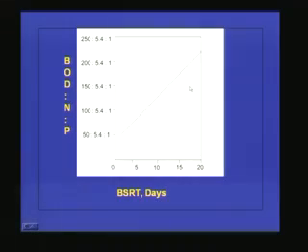What I mean is, if some industrial wastewater is there and there is not sufficient nutrients present in the system and external addition of this nutrient is costly, so we can go for a system which requires least nutrients, that means extended aeration system. So, depending upon the nutrient availability and the requirement, we can make the choice according to our convenience.